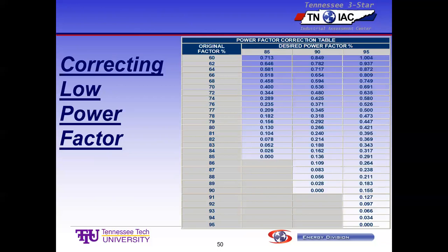So what you could do is put in a switching bank. Let's say we have to put in 1,000 kVAR of capacitors. We could put in five 200 kVAR banks, and they have control systems that monitor the power factor and switch those in and out of the circuit to give you a fairly stable power factor, so that you don't way overcorrect or, other times, way undercorrect. That's called a switching bank. And that's a good idea. It just ups the cost. If you can get by with one big static bank, well, it's cheaper.